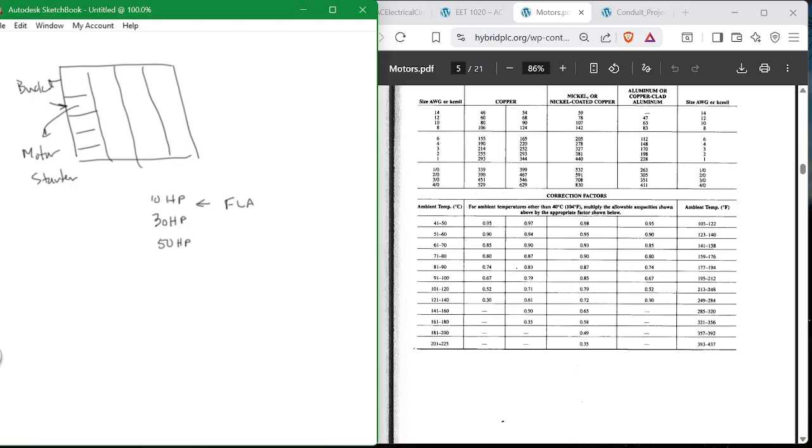You can say, I've got a 50 horsepower motor, but I'm only using a 10 horsepower load. What happens? It's running inefficiently. Okay. Motors run most efficiently when they're at full load. If they're not at full load, they don't run efficiently. So all that said, you want to get as close to 50 horsepower as you can if you're running a 50 horsepower load. But loads vary. Sometimes you have something on the conveyor, sometimes you don't. Sometimes there's a heavier load on the conveyor than at other times.